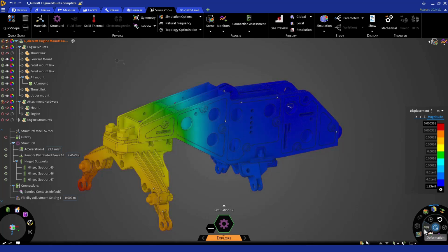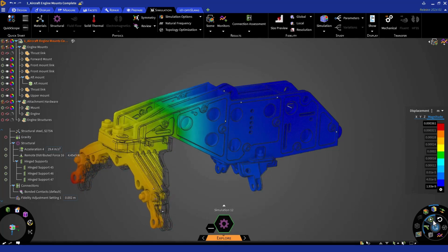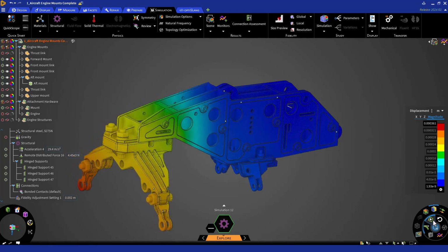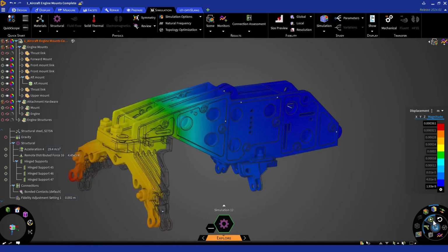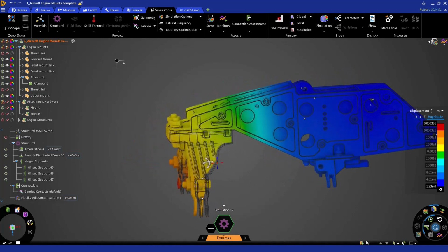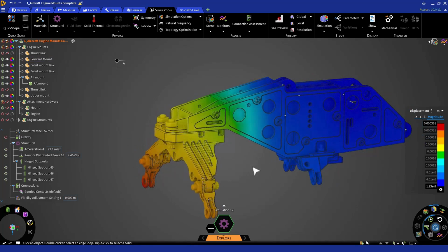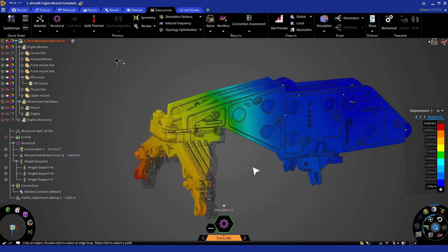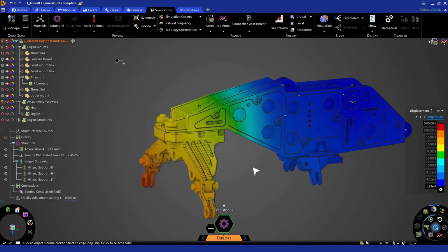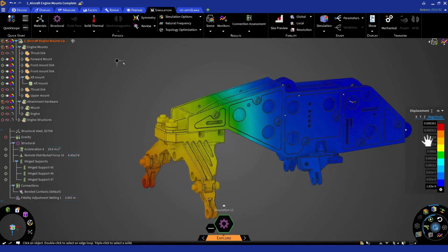We can view the displacement results and the deformed bodies to verify everything is behaving as expected. We'll be able to see the connectivity between multiple bodies, and we can see that we have forward and side motion as expected. There are seemingly large displacements at the forward mountings, particularly if you have scale deflections on. But note that adjusting to true deformations and reading the legend will show displacements are very small. Let's wrap up this initial assembly simulation by reviewing additional results available. In the legend, we can see contact stress results are now available for post-processing.